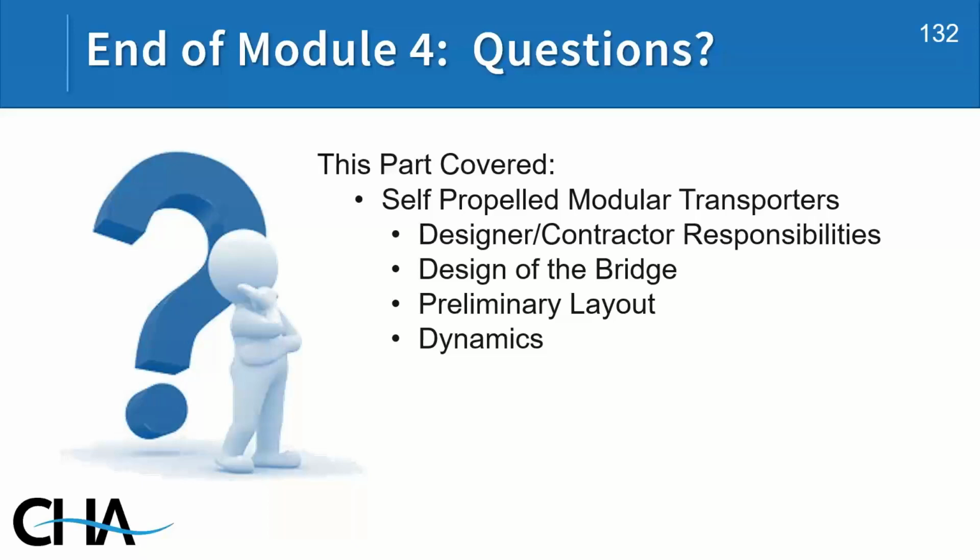As far as designing those foundations, the contractor is responsible for designing the foundations because it is a temporary works situation, and we want the contractors to have the flexibility to design either a deep or shallow foundation, and both have been used. So we give the geotechnical parameters. In some cases, we actually do a geotechnical report for the temporary abutments with a recommended pile load or recommended soil pressure. But at the very least, we recommend designers give borings to the contractor so they can design their temporary foundations. I think I answered the whole thing?